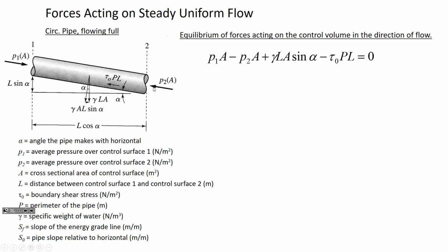And so what we can also say is that there is a shear force that's pushing to the left. It's the resistance, or the pipe friction, in the opposite direction of flow. Here, the water is flowing from 1 towards 2, so that means to the right. So you'll notice this arrow, that's representing the pipe friction force that's being applied.